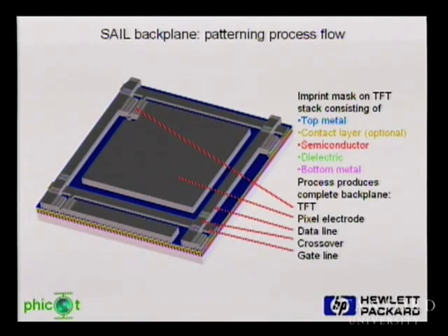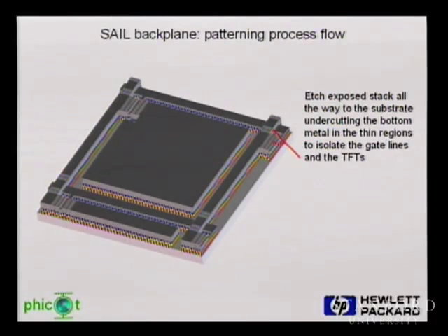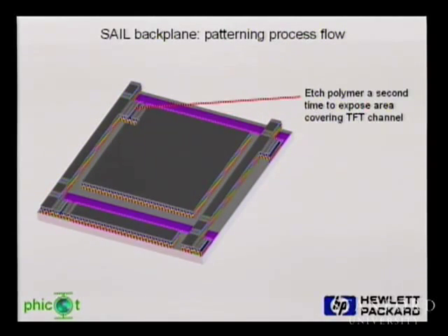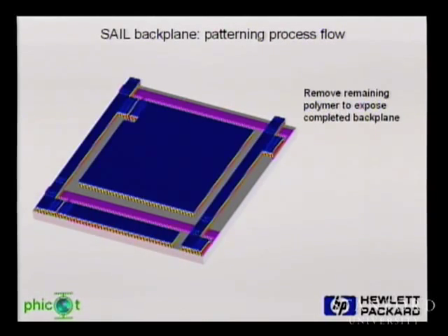So here's an animation showing the steps of that. What we have in blue and down are all the device layers that we've put down. On top of this is a molded structure, this three-dimensional thing. The way we transfer the pattern information is alternately by etching the mask and then the device layers. We go back and forth. We'll etch the mask some, which changes the shape of what's being covered, and then we transfer that into the relevant layers of the device. I'll go through this quickly showing how we're going back and forth, and you probably won't catch it all from that.